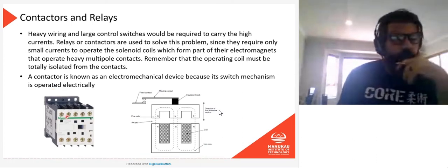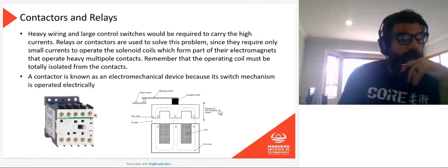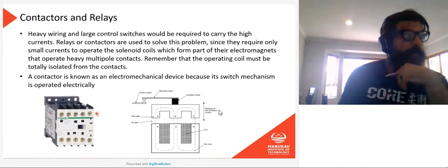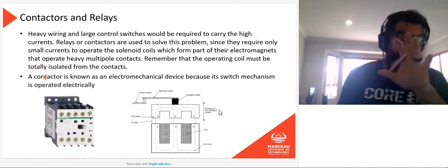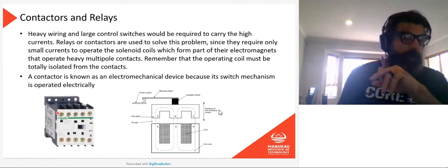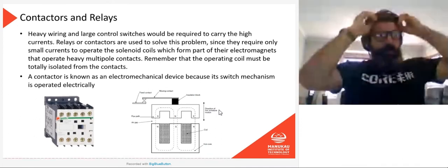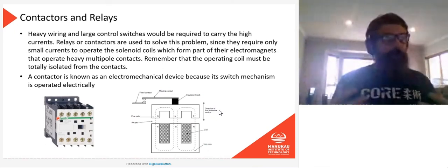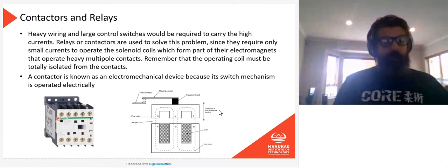from the circuit breaker, then the power to my power terminal and the power to my coil will be switched off at the same time. If we have 2 entirely different power sources, there's a possibility that we could have power on here, but power off here, or power off here and power still on here, which could get dangerous, but it would depend on the situation. Without going into a huge amount of detail on all the different ways and places we might use contactors like this, it's really hard to say how we would go about doing it.